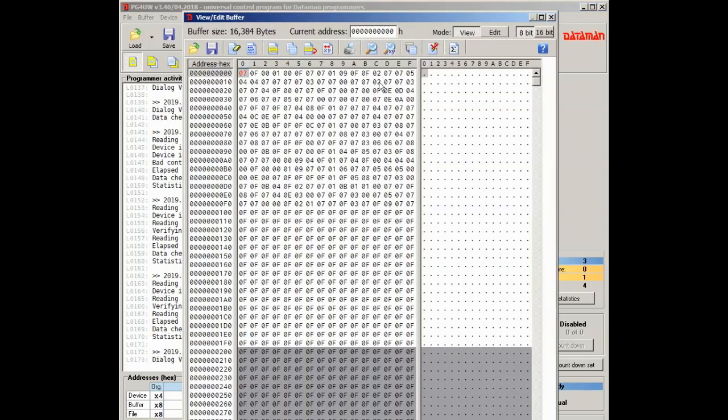So it's just the first 256 nibbles that we're looking at, or 256 bytes. The high nibble of the byte is masked off for this particular device, and surprisingly the data appears to be correct. I wasn't really expecting that, but the ROM appears to be working.